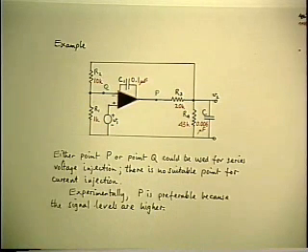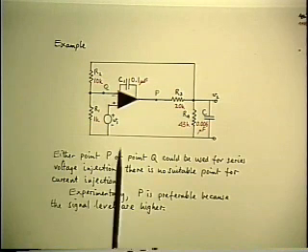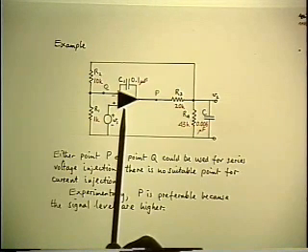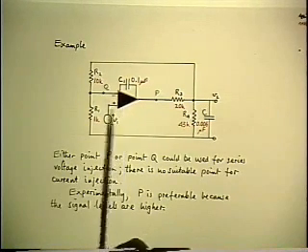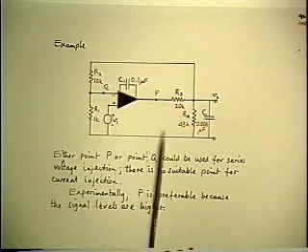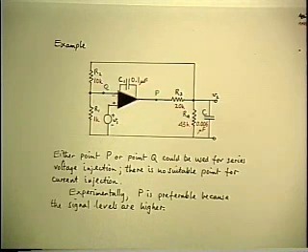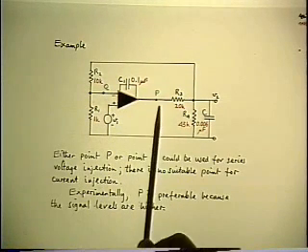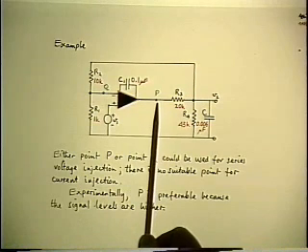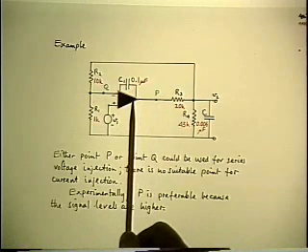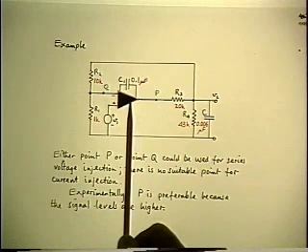Okay, that means we still have to choose an injection point. And since we'd obviously like to match it on the bench eventually, that imposes some limitations on the choice of injection point, because we're not going to be able to do it inside the chip. So we're limited to an injection point that is outside, and we don't have many choices. One of them is the point P, because the data sheet says that the output impedance of the op amp is very low.